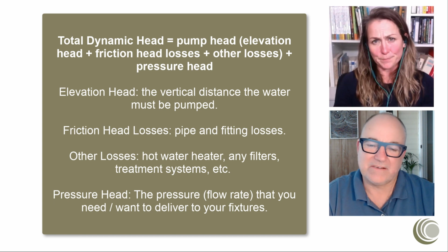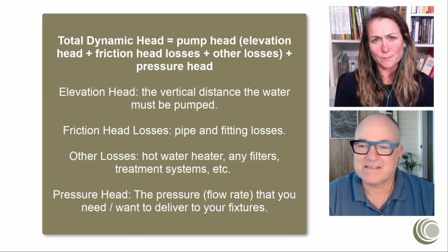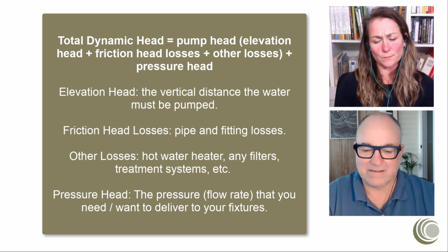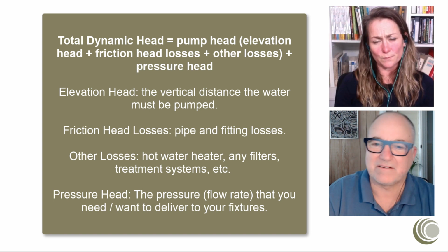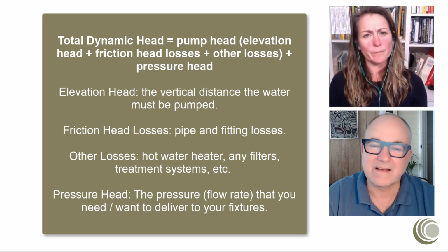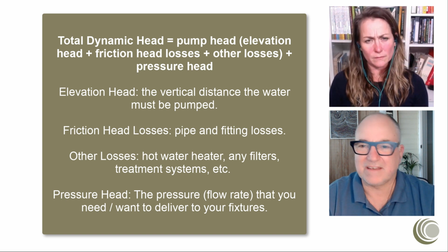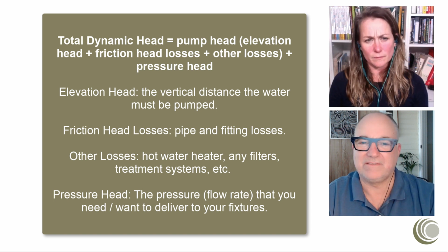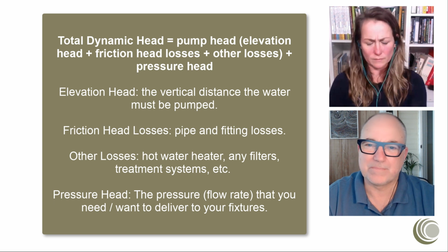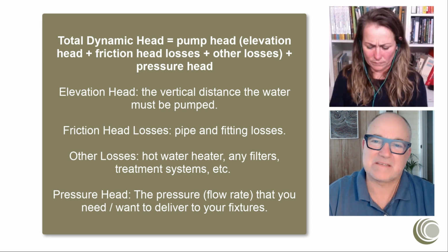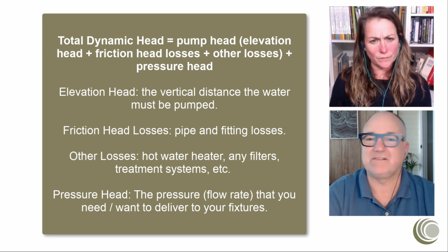Yeah, and it's very important to draw a little sketch of your house when you're thinking about this problem. You've got the horizontal plan of the house and your rainwater harvesting system, which is an important part of the sketching and thinking about it. But there needs to be a little vertical plan of, well, my pump is down here, and here's the highest point where it needs to supply water to.